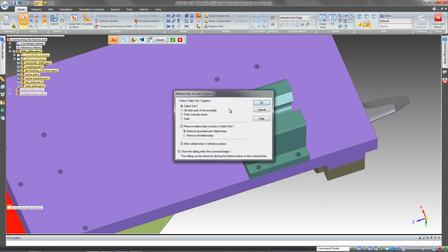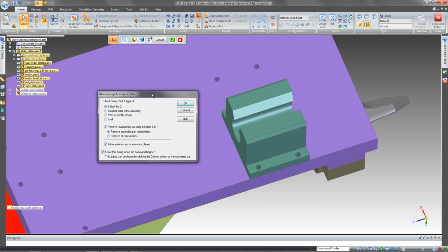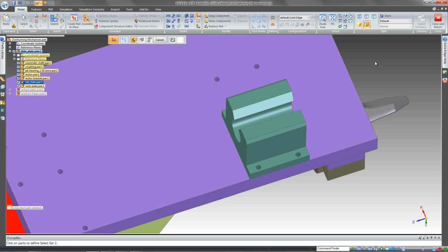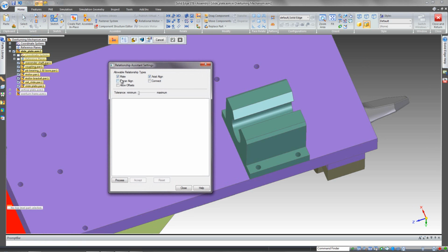And for the example that we're going to show, I'm just going to do this tool on 2 different components. I'm just going to show how it works. But you can actually do this on the entire assembly if you'd like. But what I'm going to do is tell Solid Edge to look at these 2 components that I've selected. And what I want you to do is if you find mating conditions or axial alignments or planar alignments as well as offset options, go ahead and apply those assembly constraints automatically for me.